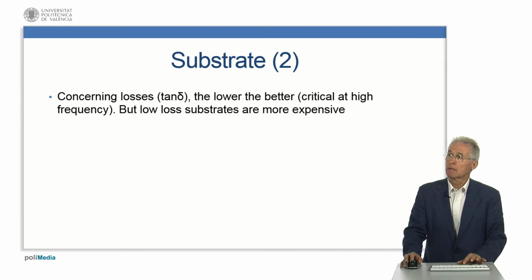Concerning losses that are represented by the loss tangent, the lower the better. This is critical mainly at high frequency, but low loss substrates are more expensive.